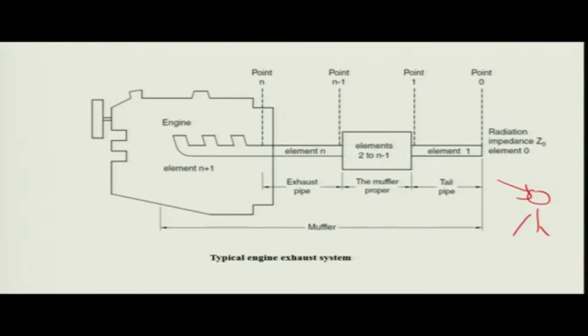So basically you say that the muffler is doing its job, it is a well designed muffler, and you are happy. So how do you define that? What is the quantity? Suppose when this was not there, and only this part was there, it was making a lot of noise. We will call this LW1, that is basically the acoustic power. Remember, W was used to denote the acoustic power, and SPL was used to denote the sound pressure level.